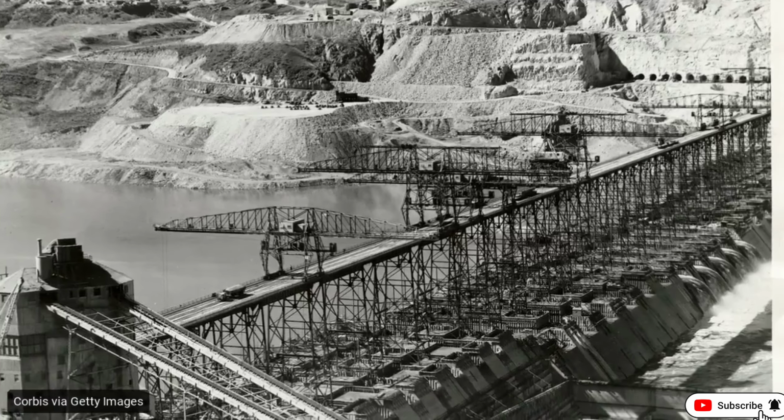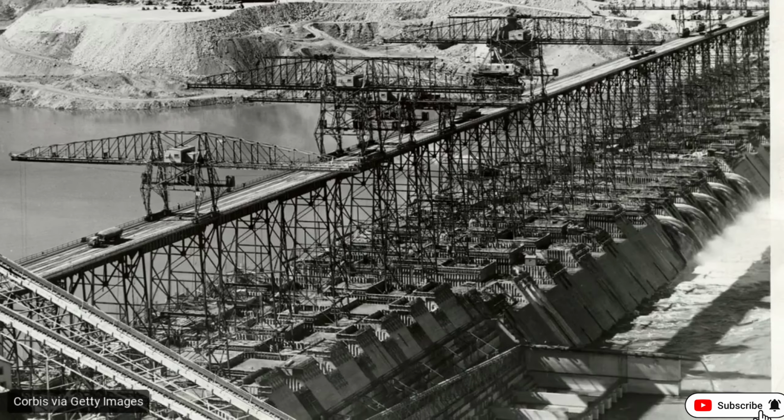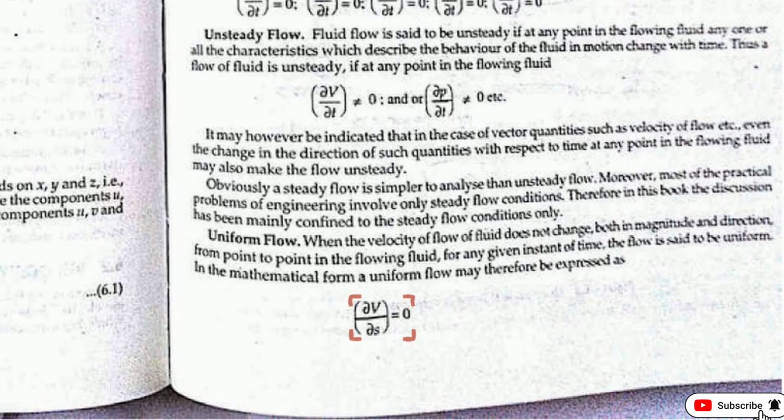To build a structure that will last a century, the data at that Eulerian point must be predictable. Look at these partial derivatives for steady flow. They equal 0, proving pressure and velocity don't fluctuate over time at a specific point. Then there's uniform flow, where velocity remains constant from one point to the next along the entire channel.